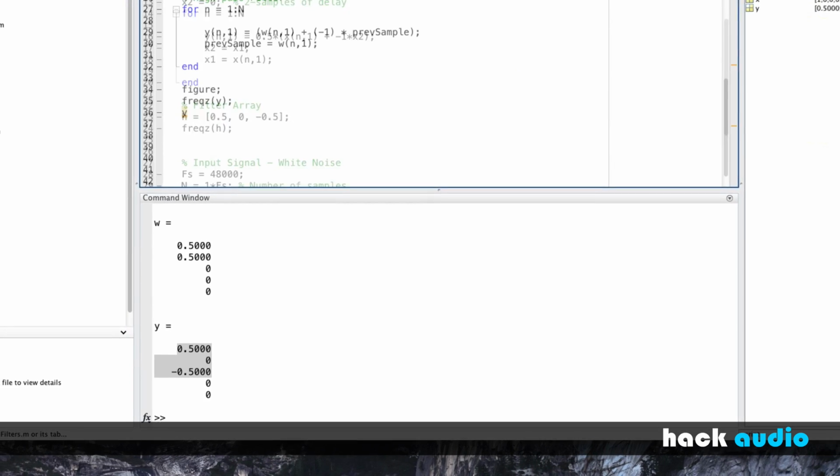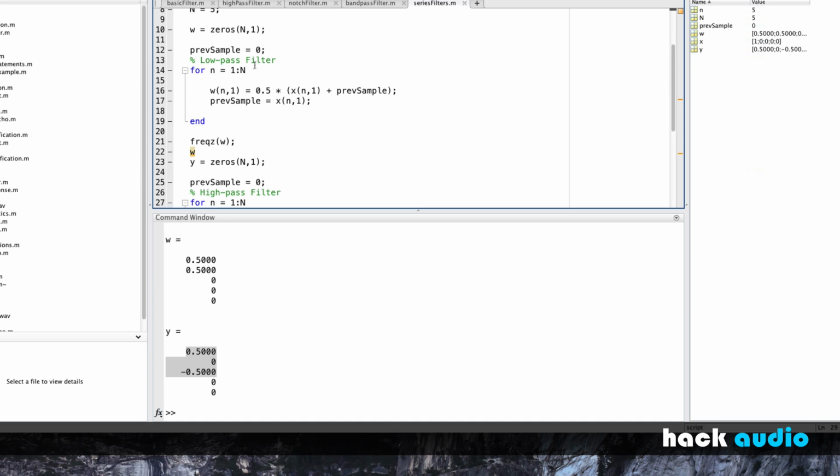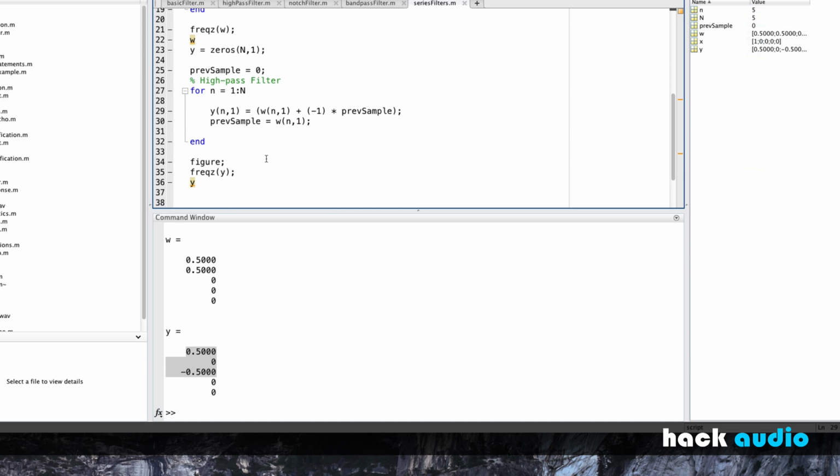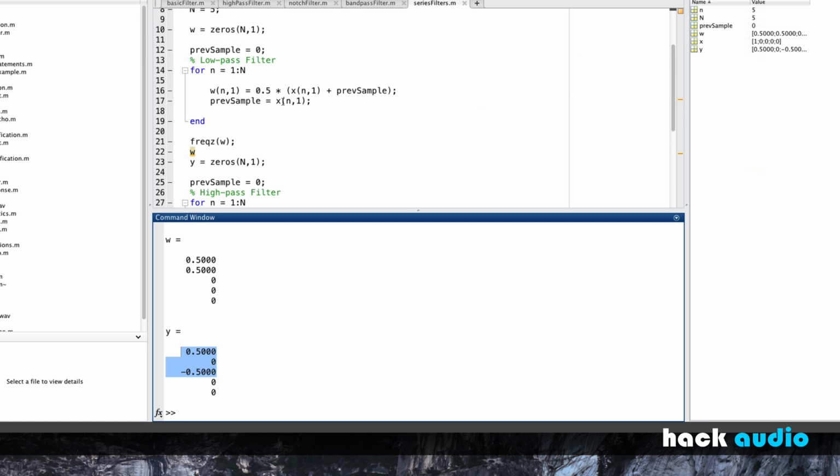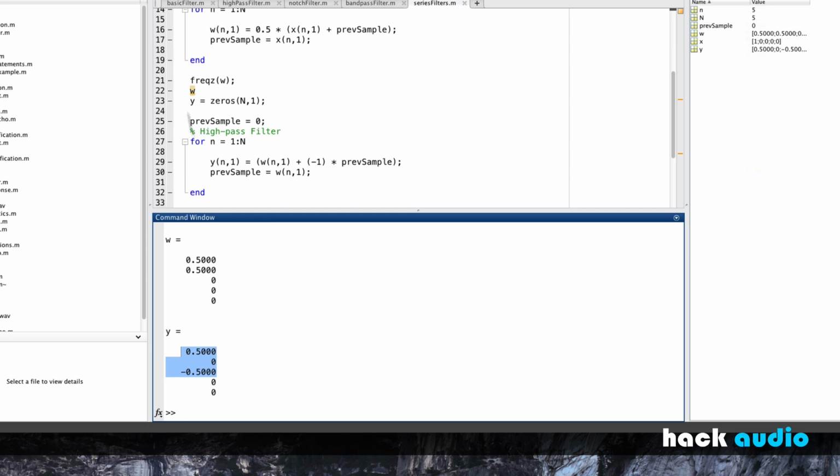So another thing to point out here is that when we put multiple filters like this together in series, we can rearrange the entire filter and just create it using parallel processing of one sample of delay, two samples of delay, three samples of delay, and four samples of delay. So different ways to think about it. If it's helpful to say, all right, if I want to create a bandpass filter, low pass followed by high pass, then what our impulse response tells us is the combined thing as this standard way of setting up parallel delays, combining those together. So we've created now our bandpass filter. Hopefully that is somewhat intuitive for putting together these two filters.